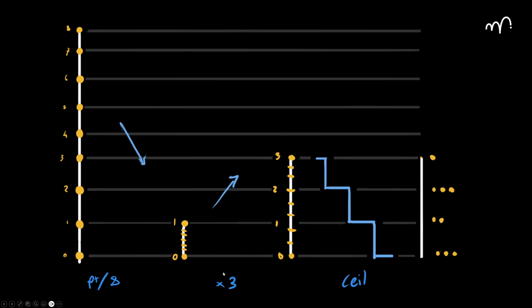And we can multiply that by the value that we actually want to split the mesh in. So let's say we want to split it in 3 chunks. We multiply this value by 3. So now we have our line resampled into a 0 to 3 space, because that's the amount that we multiplied it by. And if we then do a ceiling, which will basically move the decimals to the closest whole number.